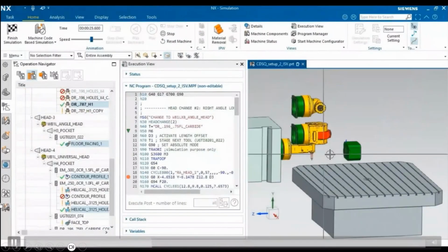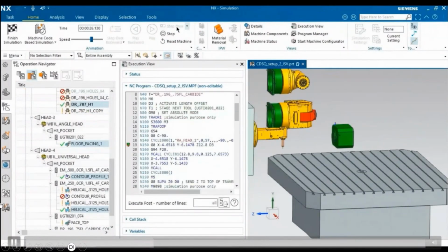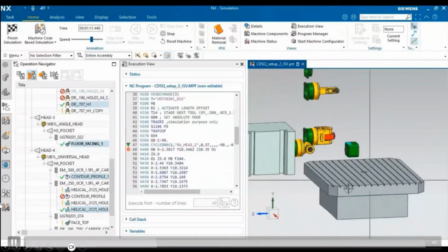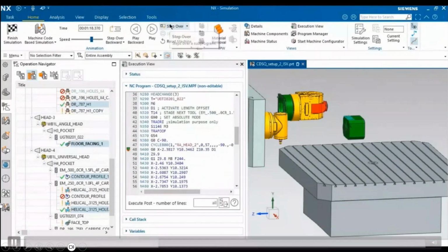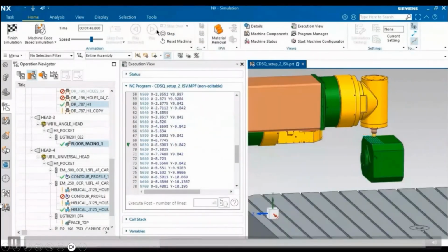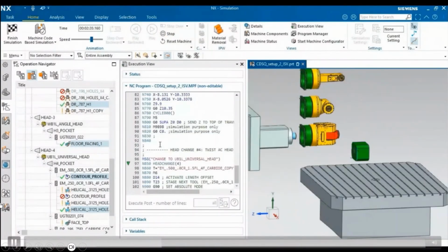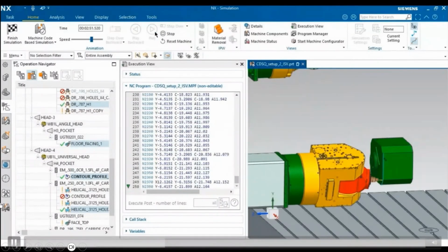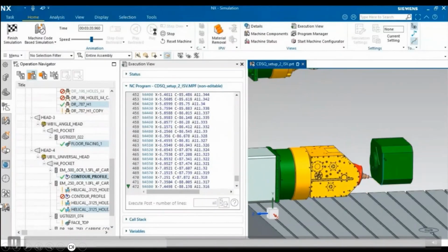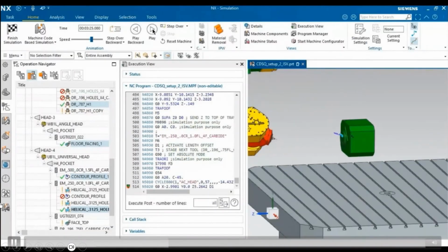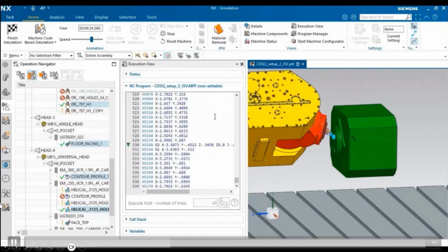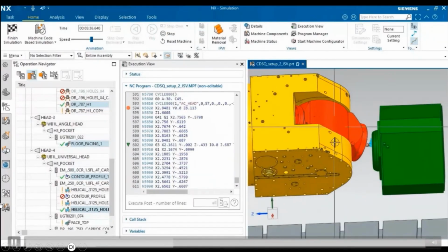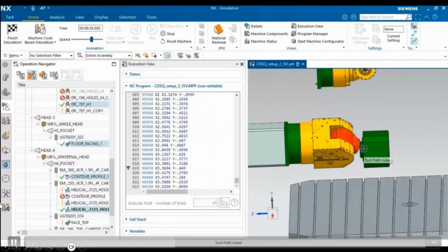This is just another example of multiple heads here. Some right angle heads that we've done with different rotaries, etc., just to be able to access different points of the part based on the setup and clearances that you have. Then here's another full 5-axis head. Notice the kinematics. Watch those kinematics working here. All right, so this simulation comes into play in these little tight areas like this. Watch how close this is going to get. However, I don't get a collision, so I know that this can be safe. There's no collision.